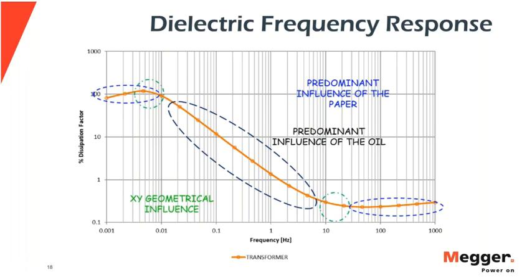But still, you can immediately see that electrical losses in the insulation become really high when we go down in frequency. Remember that power factor is reporting what percentage of the electrical field present is lost as heat. So when you're up at 100%, everything's being lost, nothing's being stored, so it's unrecoverable. But thank goodness that we're operating electrical equipment at 50 or 60 hertz over here, or we'd be having a Thomas Edison deja vu.